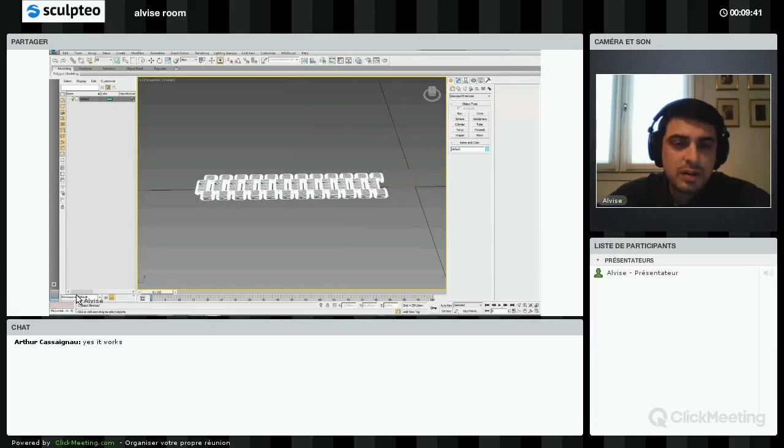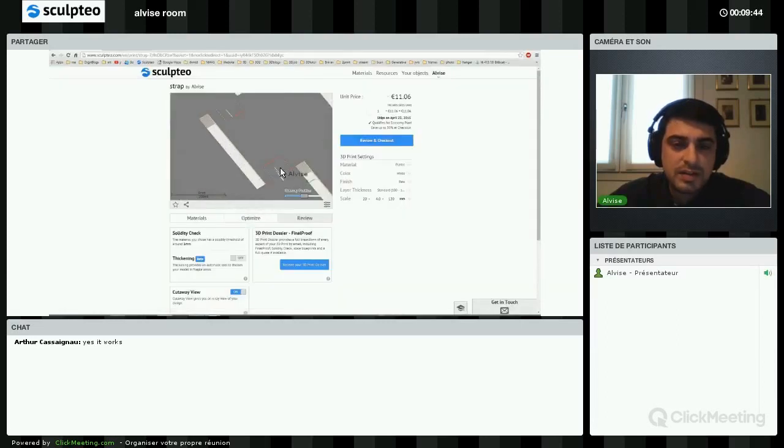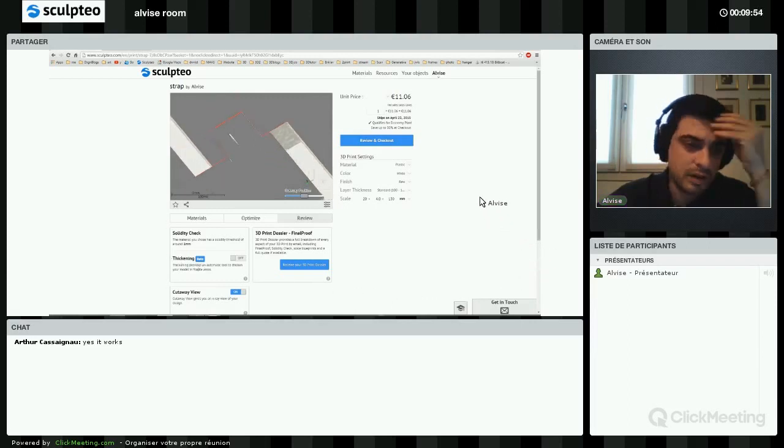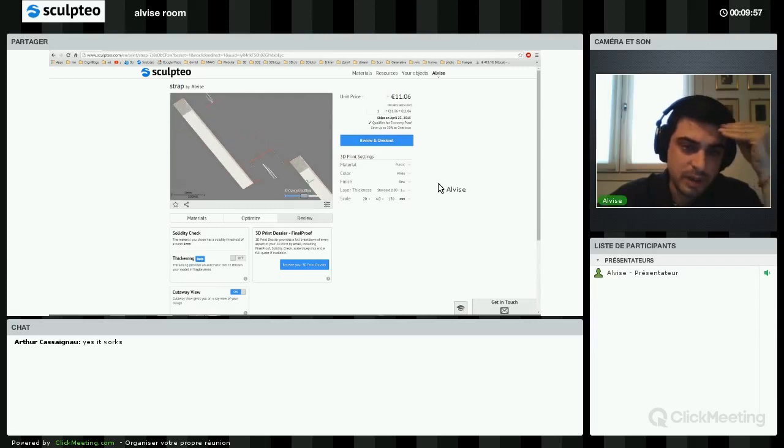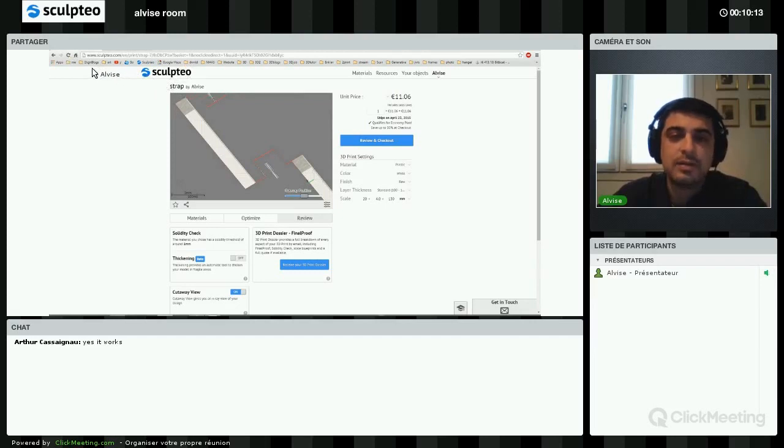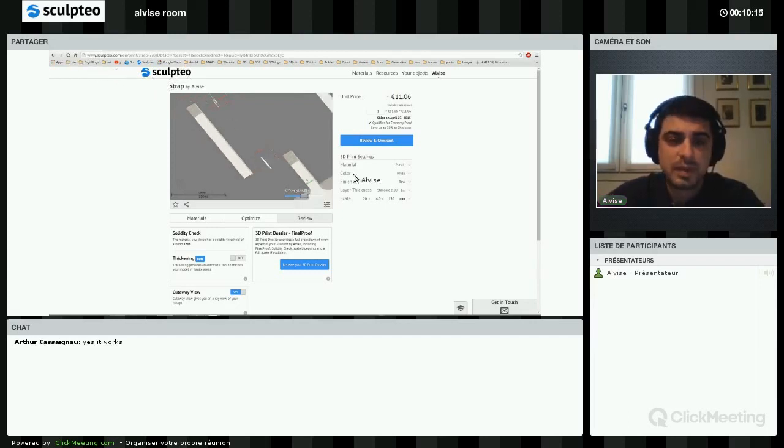So I will say this face, I want to move it more inside, 0.4 further, since that's the minimum clearance for the resin material. And then this cylinder, which is containing this snap, I want to be bigger, precisely 0.4 on each side bigger, so 0.8 diameter bigger than what it is now, so that my part will be able to move.